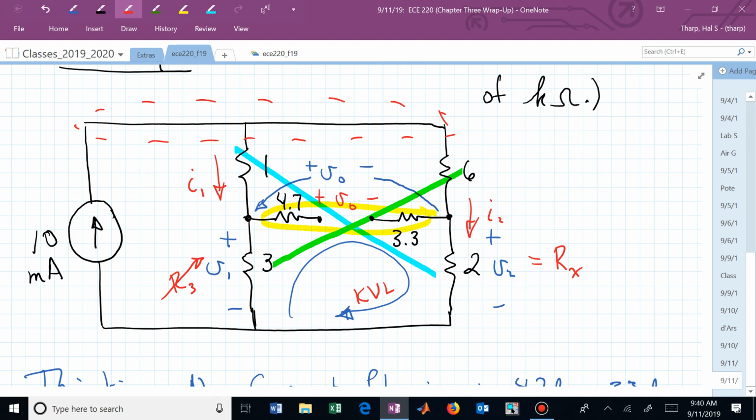Now you know what R1 and R2 are up above. You know what R3 is because you can adjust it. Now you know, because of the relationship of R1 R sub X is equal to R sub 2 R sub 3, you now can say R sub X is R2 over R1 times R sub 3, and you're adjusting this. Now you see what you adjusted it to. You know R2 and you know R1. You can now solve for R sub X.